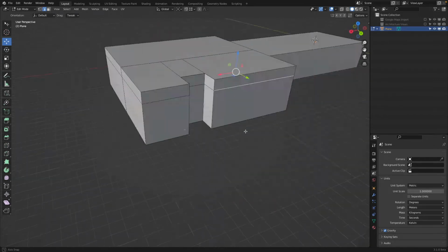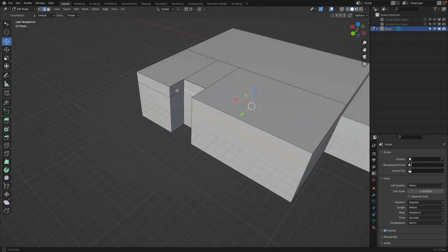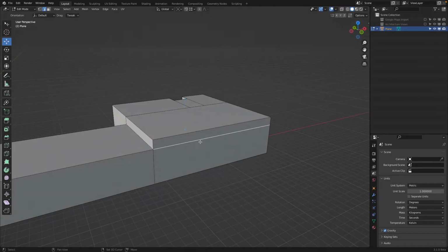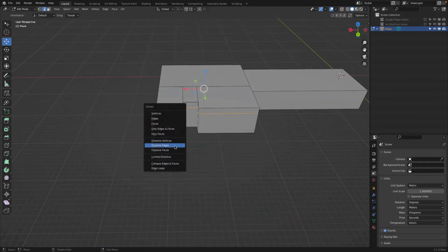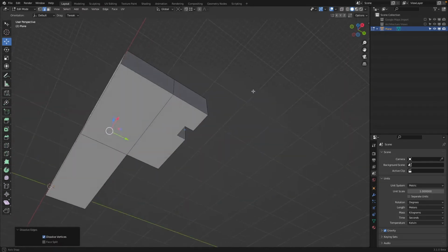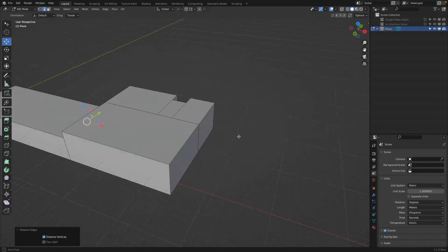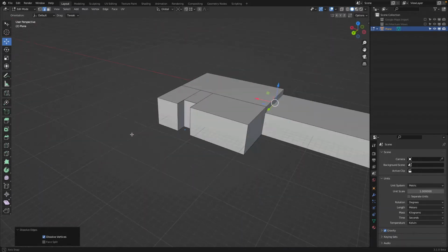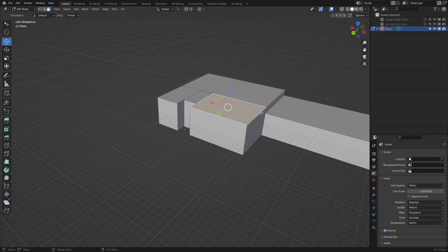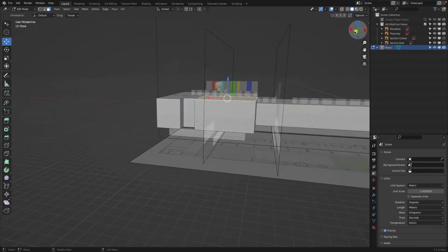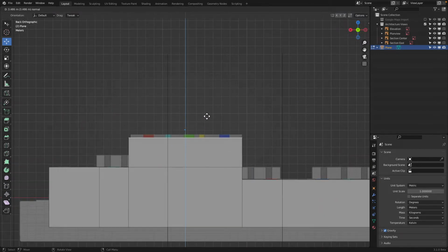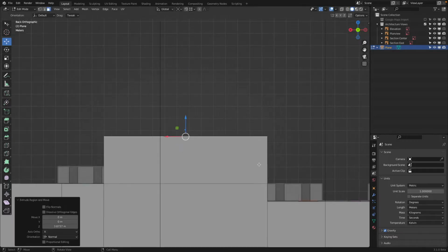At this point here, we can also see if maybe we can try cleaning up a little bit already. Maybe these lines here I select, and then I say X, and this is important, dissolve. Okay. Pretty cool, no? Very nice. So we have this piece here left. We would like to extrude this one up. Can turn on my elevation view here. E for extrude, and I move this one up, and there we are.